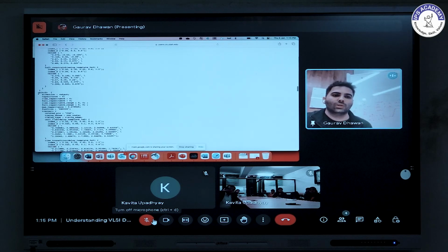Yeah, pin Q is what I wanted to show, where the direction is output. Here you see there's a timing block. In this timing block, the related pin is clock. It means that this arc is from clock to Q. Similarly, for an inverter, you will have it from A to Y.